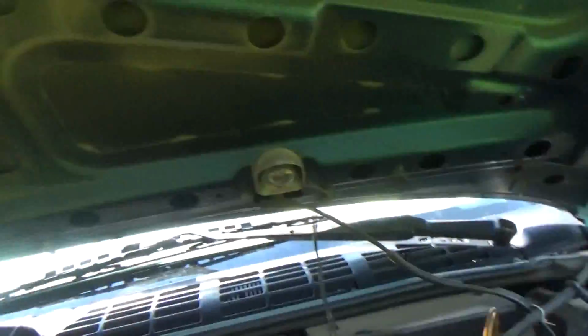If you can't locate a short to ground by a wiggle test or visual inspection, the next best thing to do is put the fuse in, take it for a spin on some bumpy roads, and see if it happens again. If it does, we'll chase the problem. If it doesn't, give it back to the customer and tell them you found a blown fuse. If it happens again, bring it back, then we'll go further. But if it's just a fuse fault due to age and heat cycles, then you fixed it. That's it. So let's pop in a new 20 amp fuse and go from there.